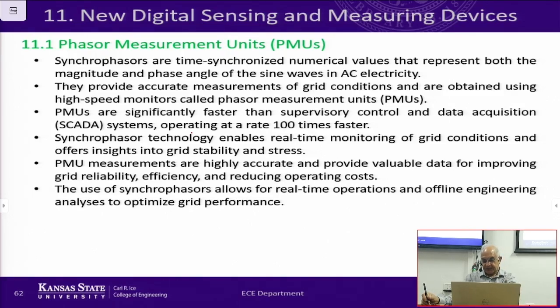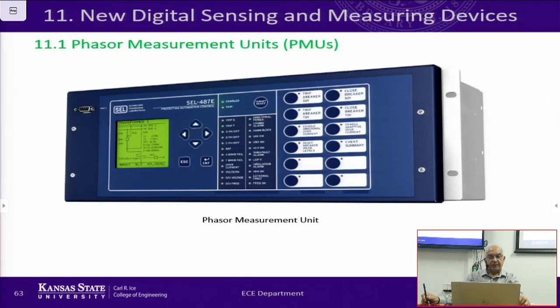And here is a picture of a phasor measurement unit. This almost looks like a relay. The same company that makes the relays also makes that PMU, and this is again a computer with fast measuring and sensing capabilities, and it also has communication to send information to other locations.